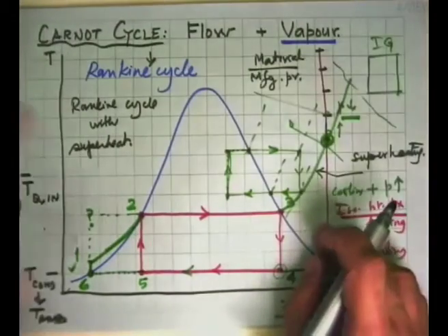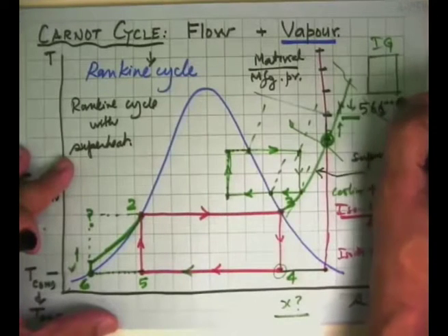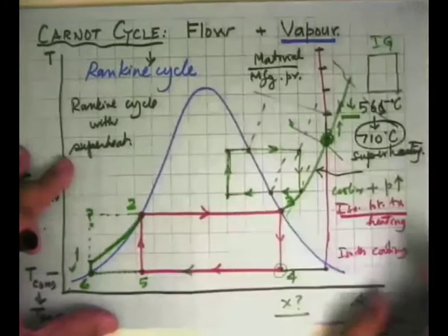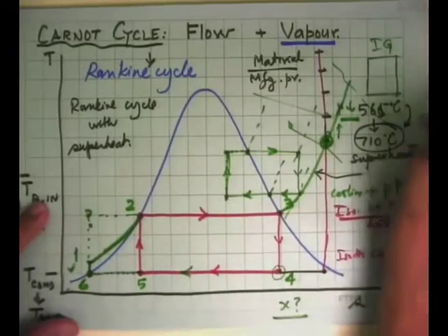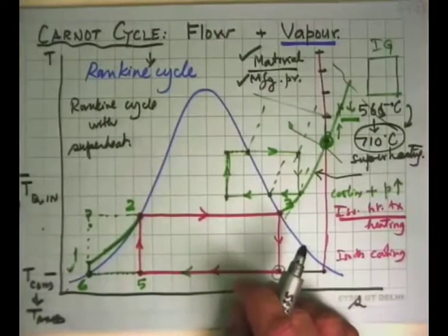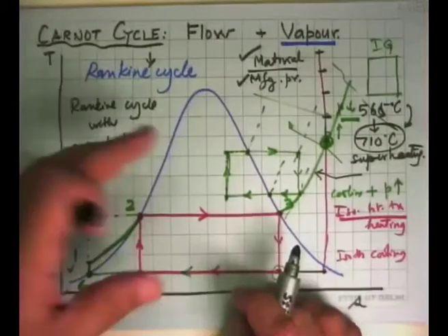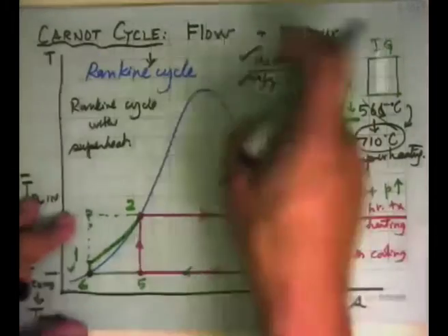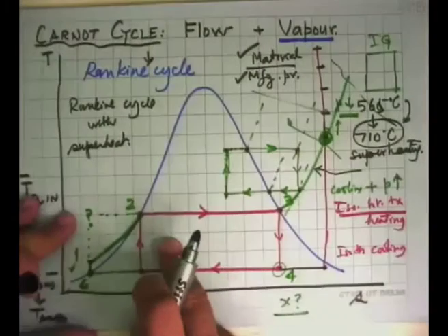And that's what's happening now also, that we are trying to increase the current limit of, say, 565 degrees Celsius. There's effort to increase this to 710 degrees Celsius. This will take another 5, 6, 8 years to happen, but the big challenge here is the material and how do we make it. The thermodynamics tells us that, look, this is what you need to do, which material to use, how do I manufacture it, what is its cost. This is where a lot of research also is going to happen. But all of that research is coming from this motivation.